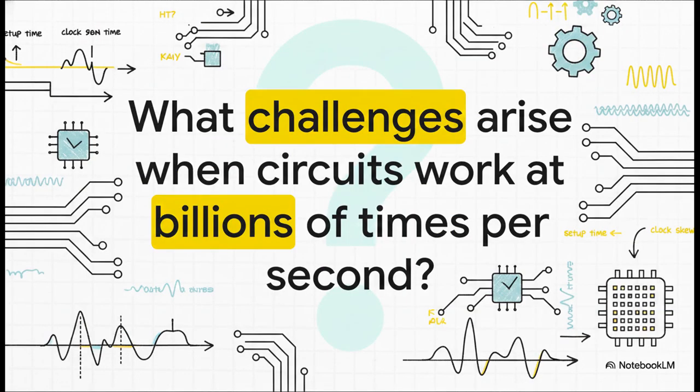Think about it. What happens when you have millions of these flip-flops all working together, all synchronized to a clock that's ticking billions of times a second? Well, new practical challenges start to appear. You'll have to learn about really important timing concepts like setup time, hold time, and clock skew to make sure your high-speed designs actually work. But that is a fascinating and advanced topic for another session.